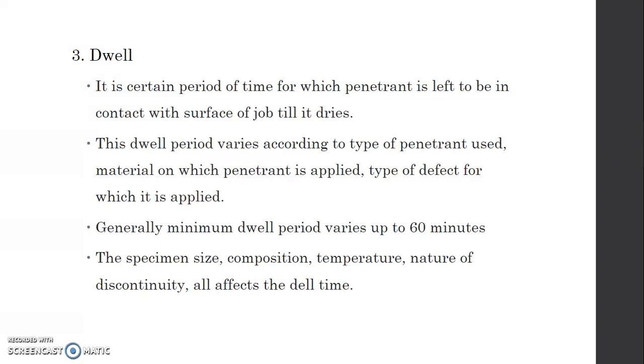Normally the minimum is 5 minutes to 60 minutes. It depends upon the surface, it depends upon the components, right? So the size of the component, the composition, temperature, and the nature of the discontinuity. So we have to wait a certain time for the penetrant to penetrate into the defects. So we have to give a certain time.